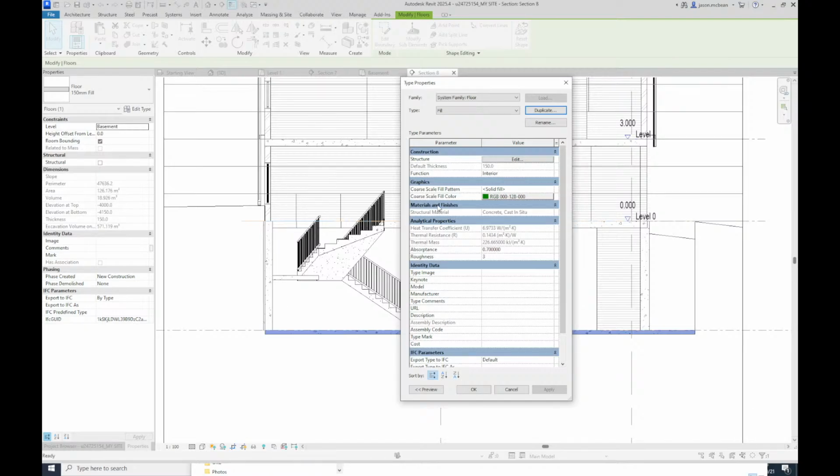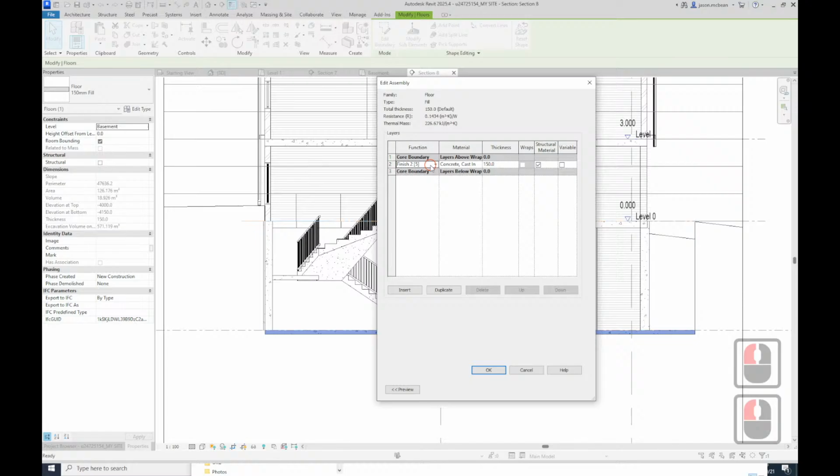I created a gap there because they'll actually put steel sheets in the ground. Because you're working close to your neighbor, there's no way that you can dig a big hole. The ground will collapse. If there's a building there, it collapses. So they're interlocking steel sheets into the ground. They've got this big machine that drives them into the ground. It forms permanent shuttering. That's why I left that 100 mil. So when I'm drafting, I know that I need to draft in a line there to represent that. Okay. I'll leave it 150, that's fine.